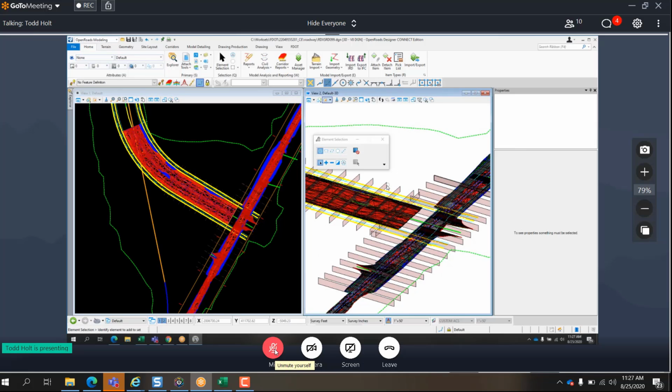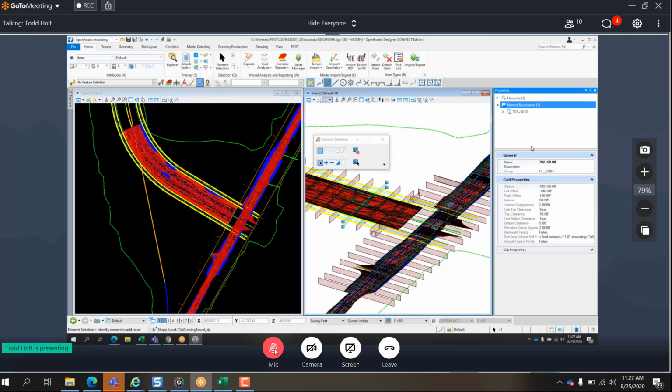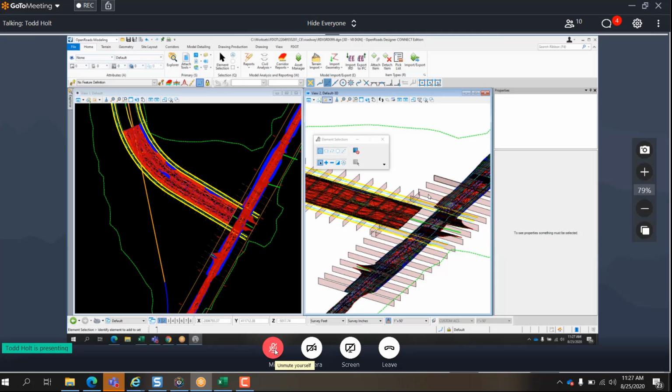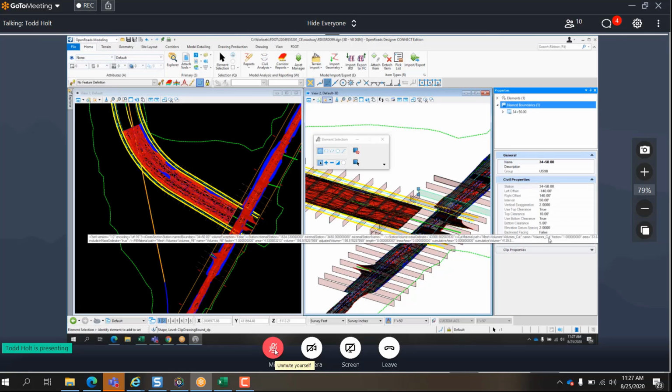So now if I look at any of these named boundaries, if I bring up the properties of that and go to the civil, you'll notice that the cut and fill volume from those reports got written into the named boundaries. If I click on either one, the US 98 or the State Road 61, I have an XML of that report cut into each of those. So at this point, I have those in there.